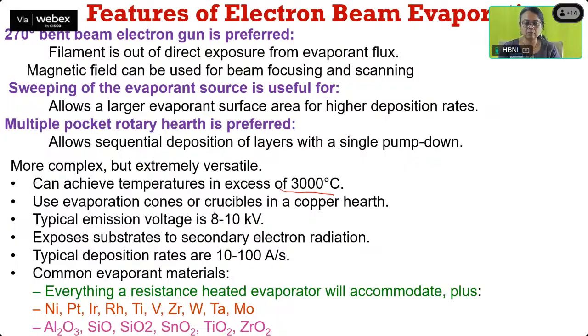So just listen slowly. My question was about gallium arsenide, GaAs. We have discussed the growth of gallium arsenide using the Czochralski technique. But the normal Czochralski technique cannot be used for the growth of gallium arsenide. So my question is why?